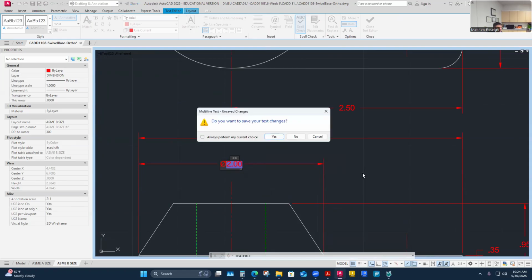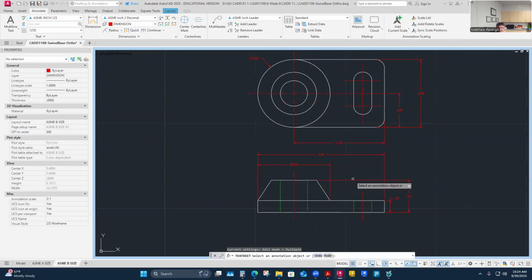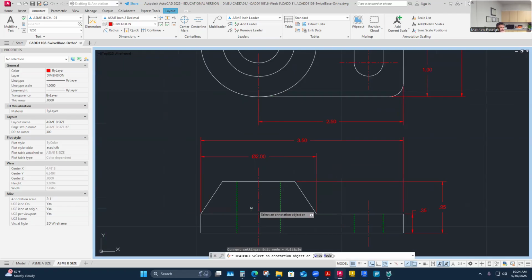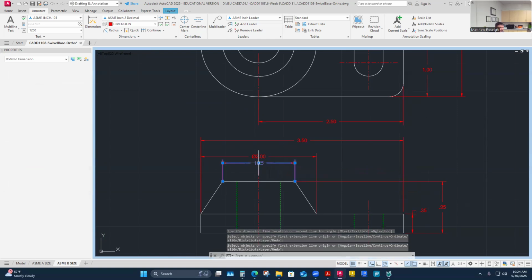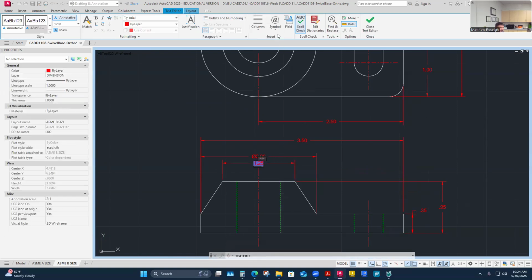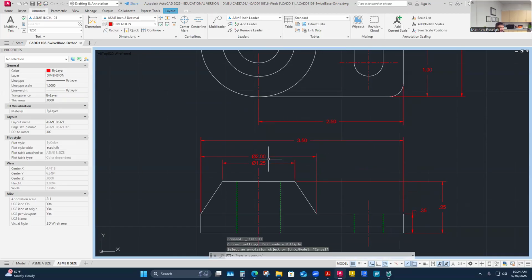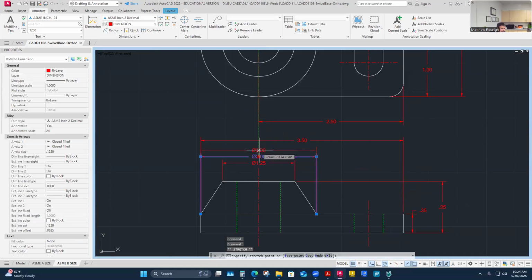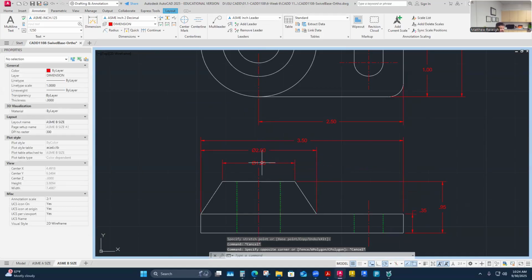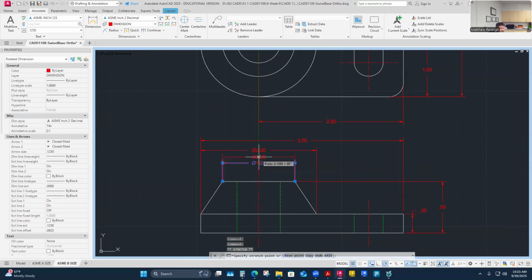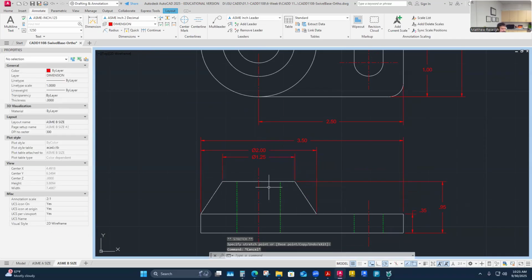So this maybe is diameter. Yeah, keep my changes because I'm thinking of the size of this cone now. That's one size with it. It's got a diameter at the base of it at 2 inches. It's got a diameter at the top at so many. I can put that here. Here's the diameter of the top right here at 1.25. This will also need a diameter symbol in front of it. So this is still size that I'm thinking of. It's got multiple sizes associated with it. It's more complex than the other cylindrical features we've done because it's cone shaped. So it's got two different diameters, a top and a bottom diameter, and then it's still got an inner bore all the way through. And that one I don't want to dimension here because of the hidden line.